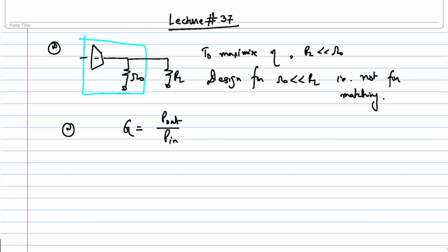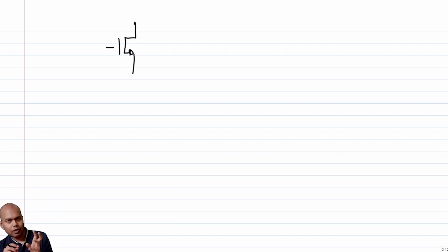But recall now that your transistor has a gate, which is a capacitor, and the gate is not a single point, right? The gate has a routing, so you'll have a resistance in the gate, and also this capacitor is distributed, which means that the signal flows in through the capacitor and goes to the source or the drain, which has a resistance also, right?